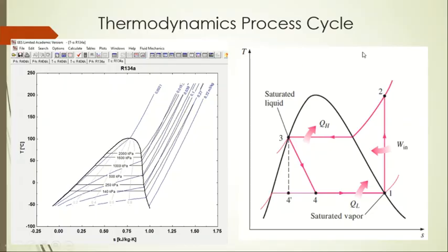Although, as I have told you, the discharge temperature of the compressor is around 60 to 65 degrees Celsius. So when they both come in contact in the condenser, it lowers its temperature to 40 degrees centigrade, and then the condensation begins in such a manner that the condenser completely condenses all the vapor entering the condenser.